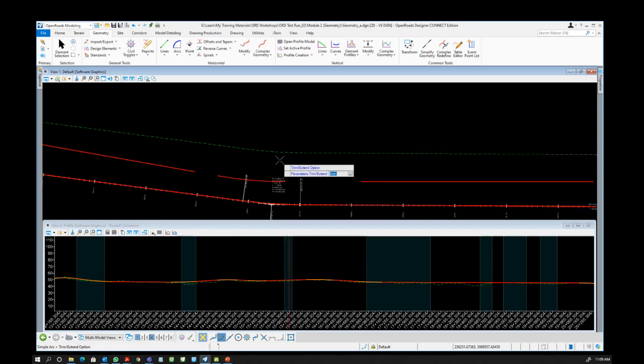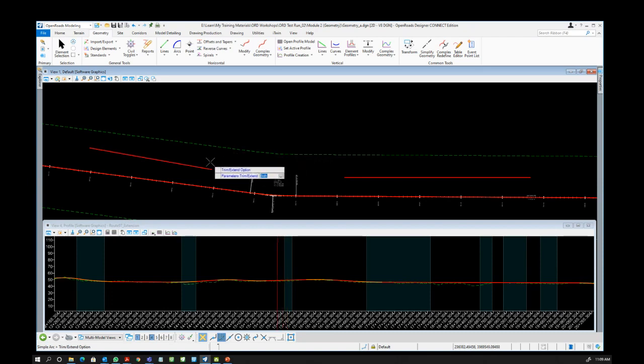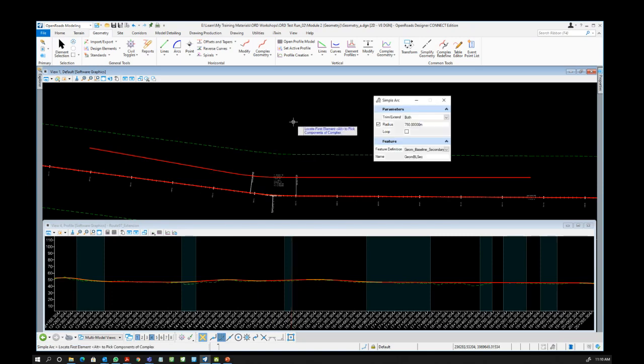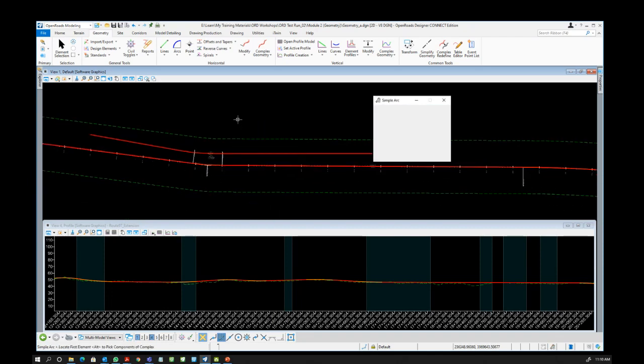Now the trimming, meaning sometimes the curve will extend to the first element and then to the second element. So I need to make sure that it's extending or trimming on both of the sides. But you can also set it, it depends on the scenario. I'm pressing the up or down arrow key now to change the trim or extend settings. So I'll just set it to both. Then I left click to accept. And then it's now connected.